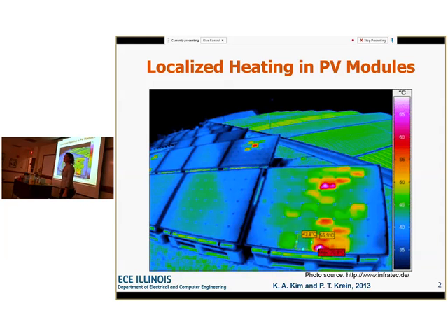That's usually when the silicon defects happen when you saw that cell, when you cut off the edges. If you have any defects, usually right. Makes sense. And the one cell that broke, it broke right on the corners too. So there's just more likely to have impurities there, that's like a weak point where it can go through the junction.